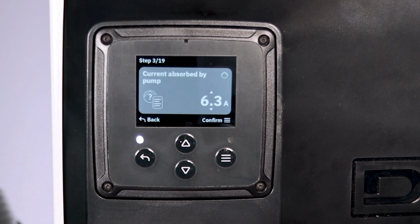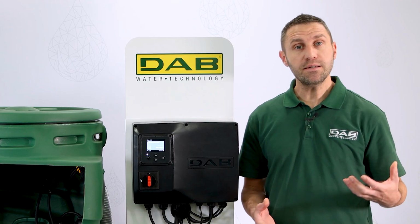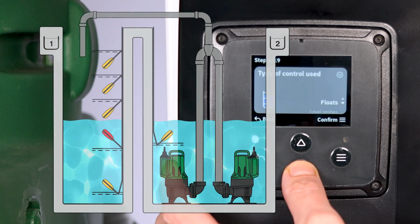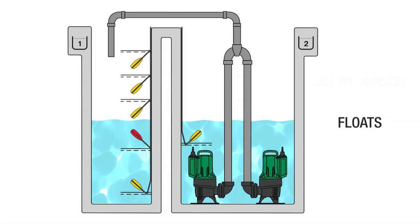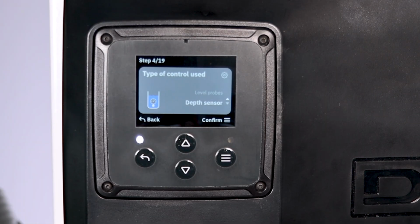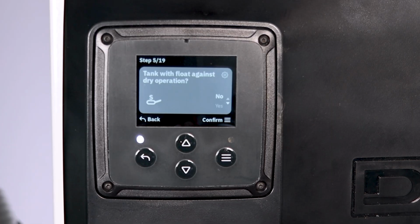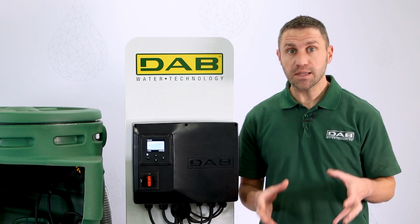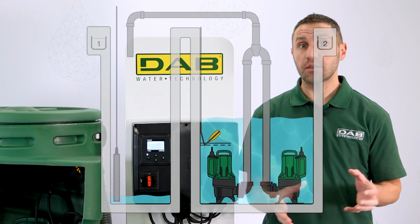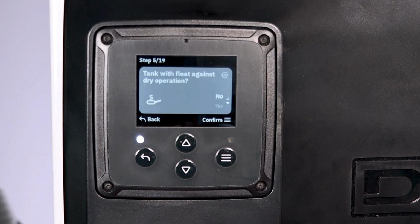I confirm that I have the correct pump amperage set. Here, I choose the type of level control that I'm using. I'm going to select the depth sensor. Do I have a dry operation float switch in the supply tank, which is the source tank with the pumps that could potentially dry run? If yes, I select it.